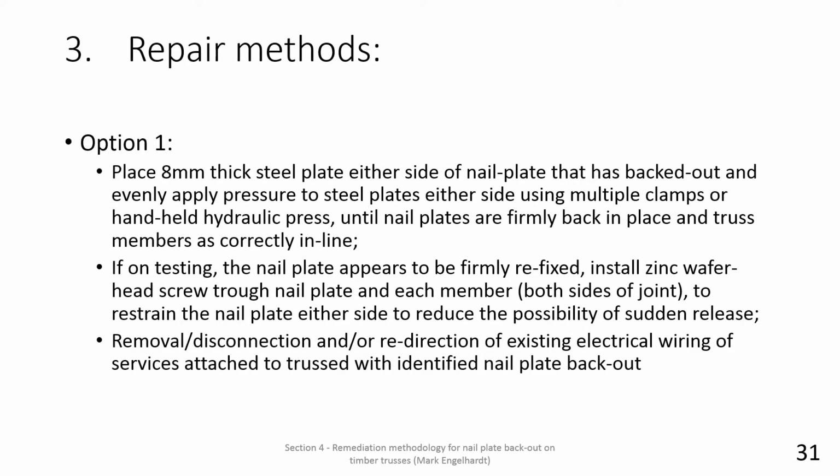Nail plate backout could be addressed by using a couple of methods. The first, option 1, is repressing the backed out nail plates to their originally factory impressed position and then providing screw fixings to retard future nail plate backout.